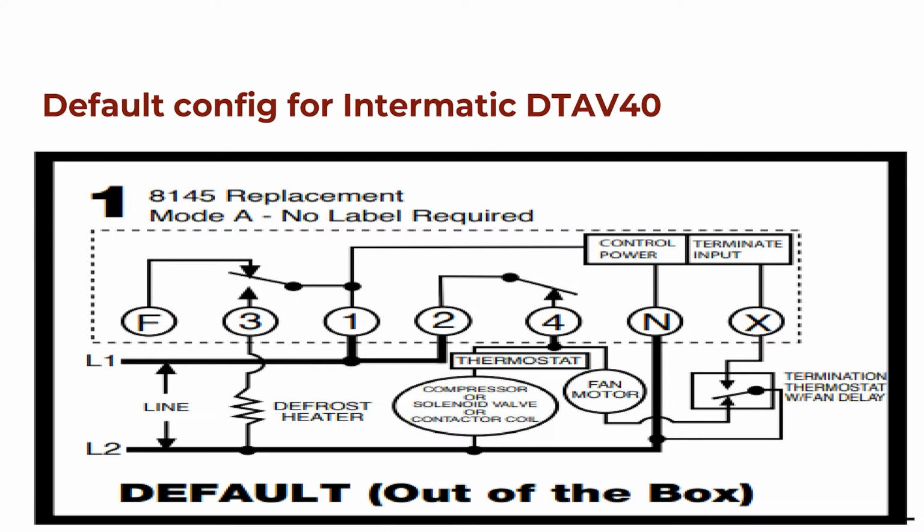But then also this other switch coming off of 3 is going to change position and then initiate defrost. So your defrost heater here will turn on, right? And so fans are turning off, compressor's turning off, defrost is turning on, right? That's pretty basic, right? That's going to be when we enter defrost. So I think that's what this was trying to tell us. This is more of a termination sensor than a fan on sensor. So I think we need to adjust that slide.